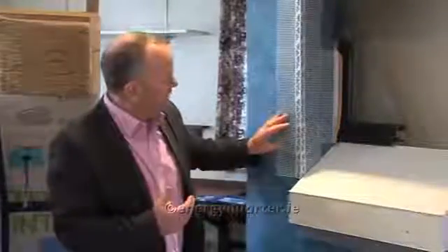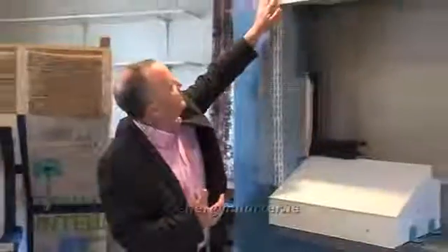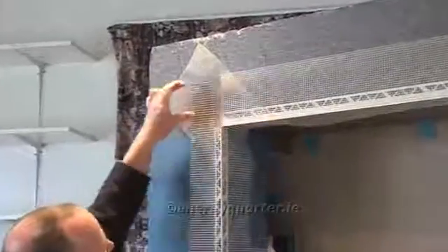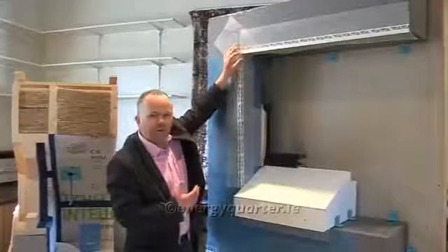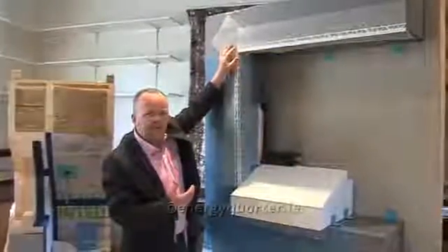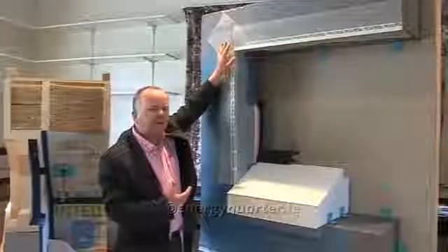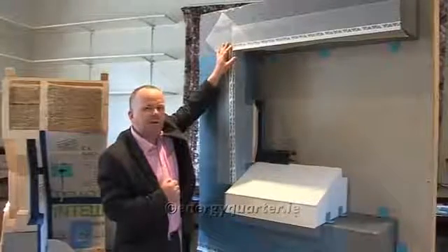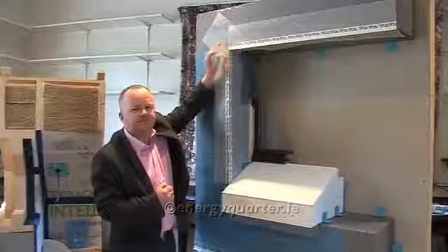So when we're using this external insulation system, we need to be very careful wherever we've got a joint or a junction, and there's a very typical detail, for example, like we've got here, where you can see there's extra reinforcing with the mesh at this junction, so that we won't get any hairline cracks or expansion cracks over time. So these kind of details are very important when you're using an external insulation system.